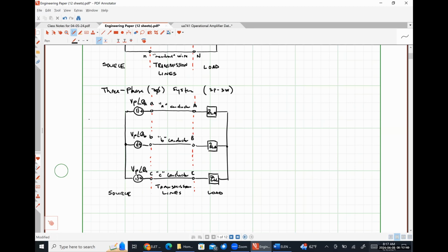So we can connect those single phase loads across different phases in order to balance the system out. We know that some of the buildings might have a heavier lighting load than others, so we tend to distribute those in order to balance everything. A three-phase system in general does allow us a lot of flexibility in order to try to keep things as balanced as we possibly can. So that's definitely a thing.